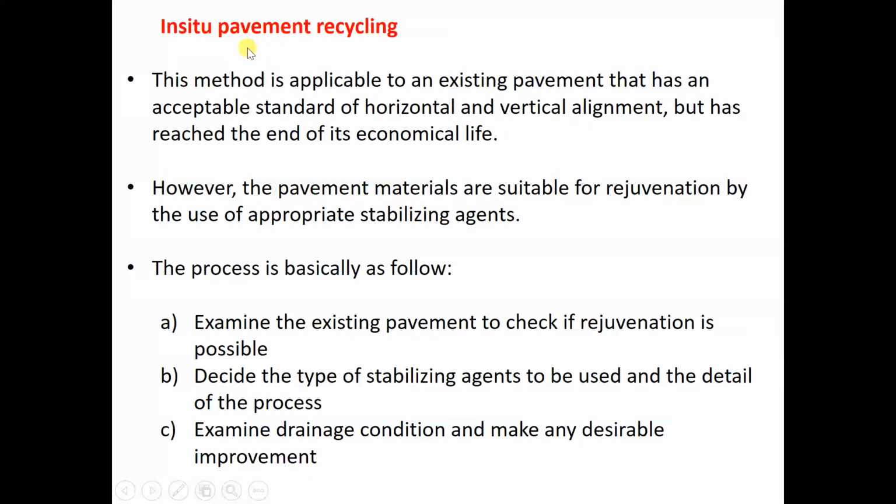That means this involves the existing pavement. This method is applicable to existing pavement that has an acceptable standard of horizontal and vertical alignment, but has reached the end of economical life. However, the pavement materials are suitable for rejuvenation by the use of appropriate stabilizing agents.